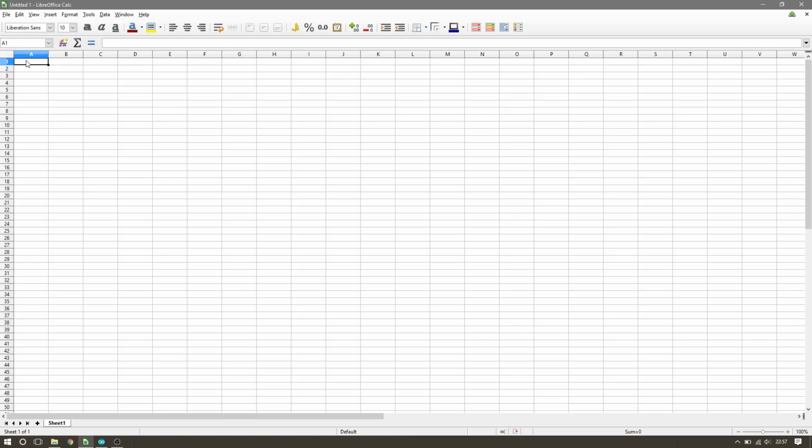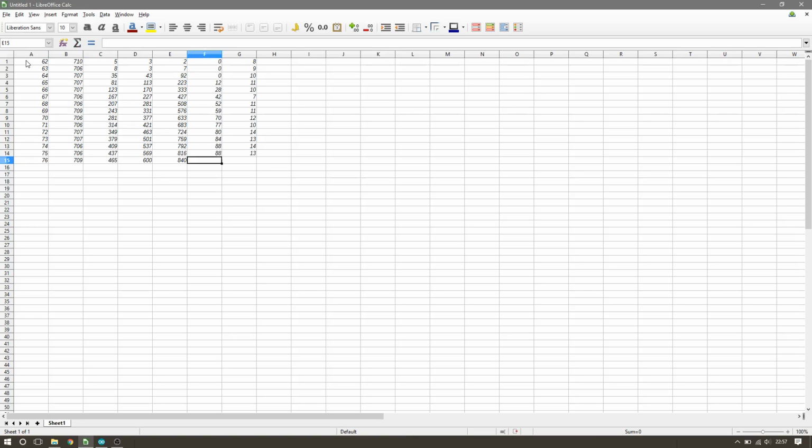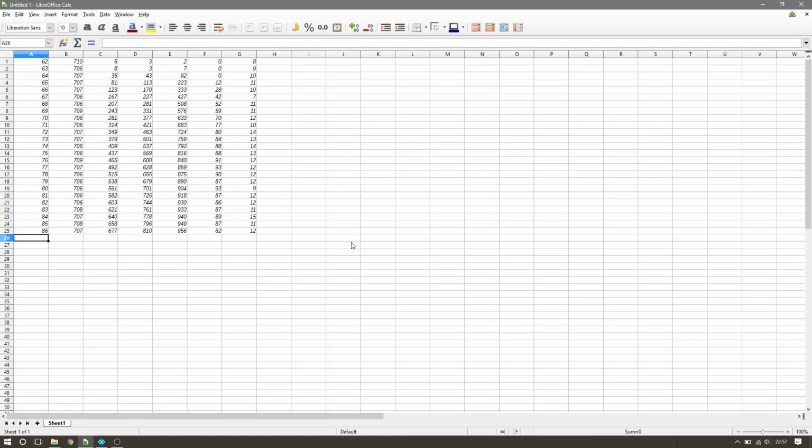data acquisition. Because I already ran this test, I'm going to re-short all of the capacitors just to make sure that they are discharged, and I will start the data acquisition now. So ignore column B and column F and G. All of the data is going to be coming from C, D, and E. So the first row is disconnected, and then after that I started connecting the actual power supply, the 5 volt rail, to the beginning of the resistor chain.